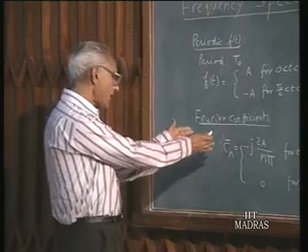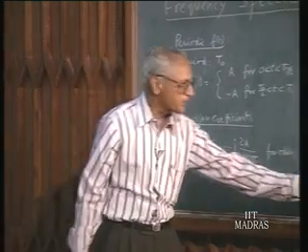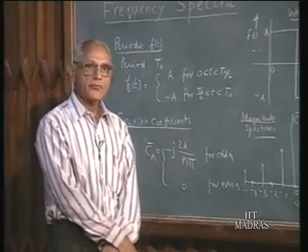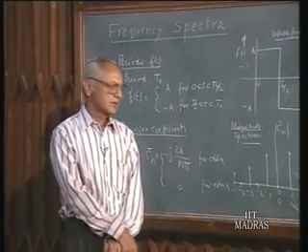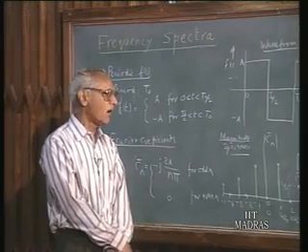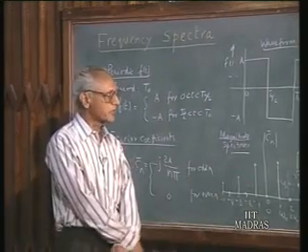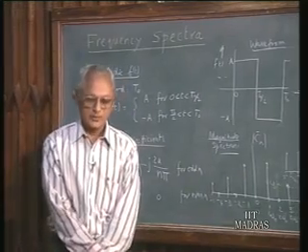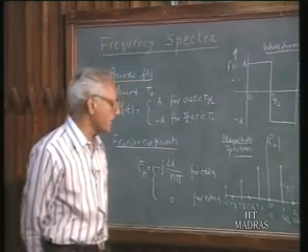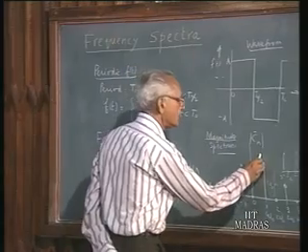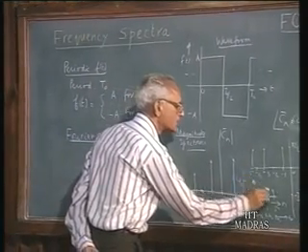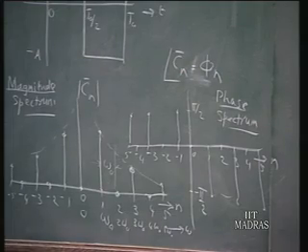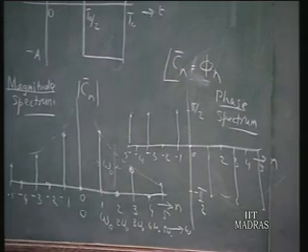So the entire information regarding Cn can be pictorially represented in this fashion. It gives you in a graphic way what are the frequency components present and what are the relative sizes. All this information is given in a pictorial representation like this. Therefore, it is often convenient and useful for us to plot the spectra of periodic waveforms in this fashion. For example, you draw an envelope like this, you can say this is how various Fourier coefficients decay for large values of n. So generalizing this,